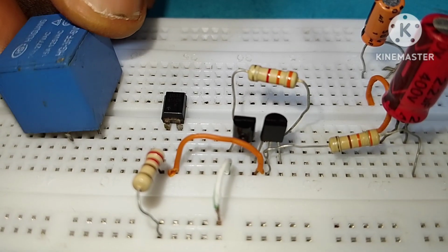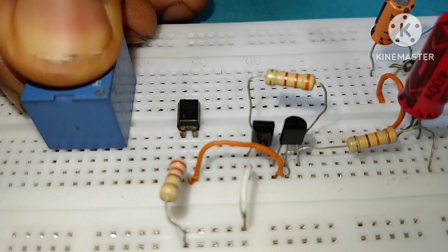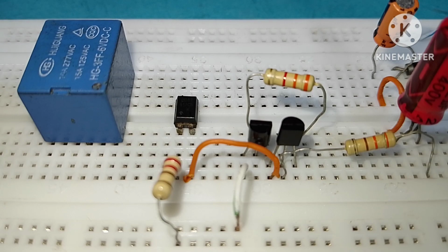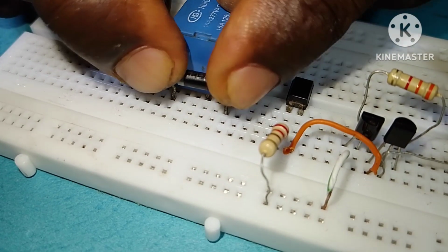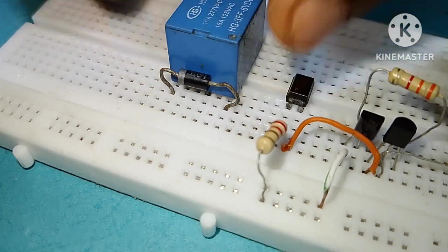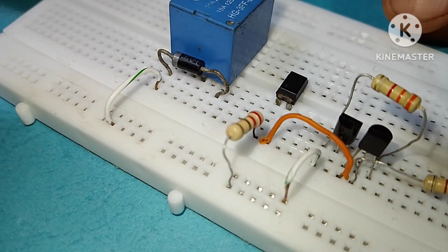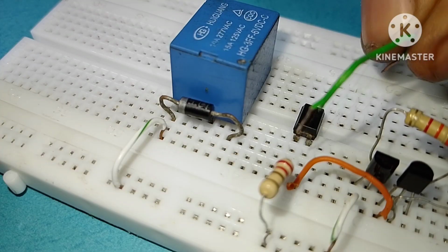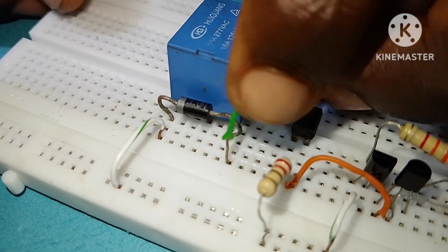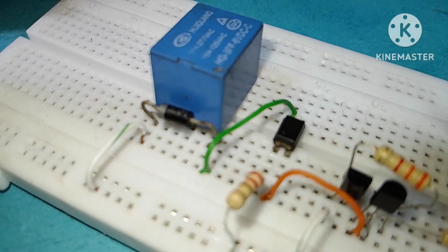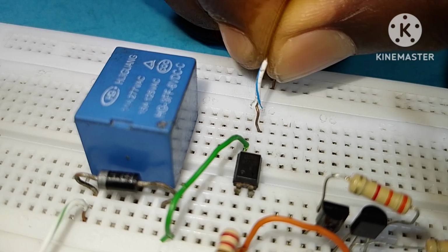And next, with a 6-volt relay, I'm using a 6-volt relay. Remember, not a 12-volt relay, a 6-volt, because I'm going to be using a 6-volt battery. And then remember to add a freewheel diode for voltage spikes. After that, connect a jumper wire from one of the leads of the coil to the positive VCC. Remember, the positive VCC. And also connect a jumper wire to the collector pin of the optocoupler and to one of the leads of the coil, and its emitter to ground.